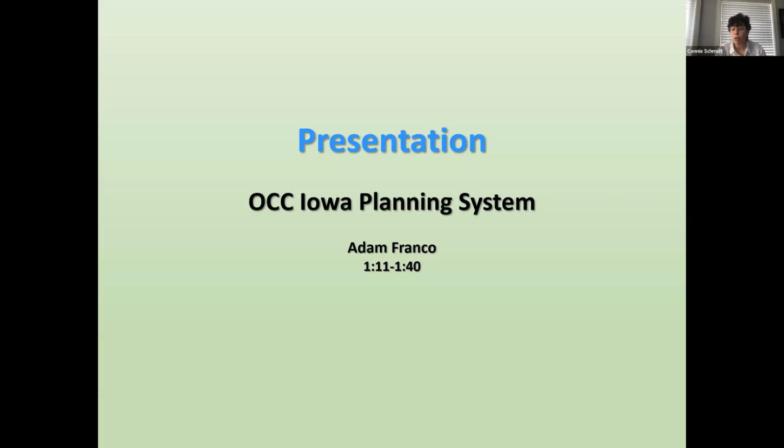It is only showing, so on the design information, let's do the design information request first. On the design information request, you indicate where your proposed project is going to be. And it uses the same database that the locate ticket uses, if you were calling in to say, I'm going to be digging in my backyard. But keep in mind, the design information request is not really a ticket. It is not going to the locator.